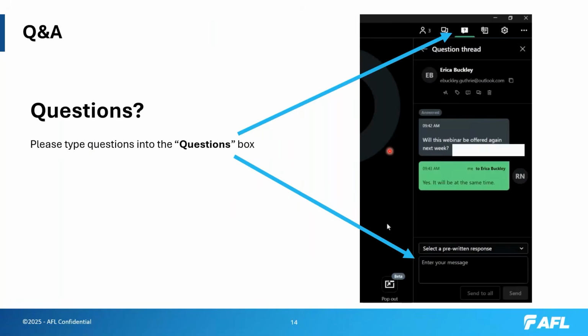That's an interesting question. The only thing I can say about that, the Fujikura FP5 sleeves for 12 fiber and 16 fiber 200 micron have been tested, thermal cycled through the various environmental conditions that they're used under, and they've passed. All sleeves are not created equal. They do use different plastic, different paraffins, different hot glue melts, so there may be some variable there you have to be aware of.